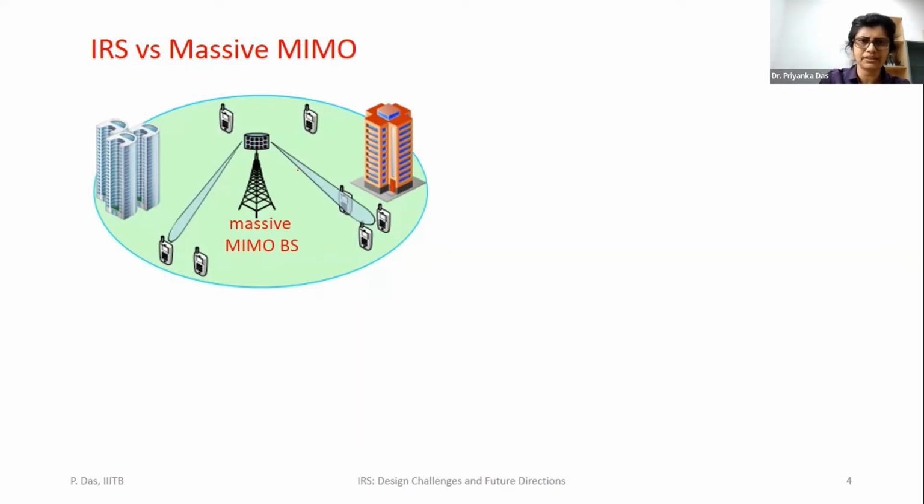The beamforming is nothing but you point the beam towards a group of users. There is a high intensity, a major lobe pointing towards this direction. Okay, you beamform another one to serve another group of users. And this is possible. This is one key advantage of massive MIMO.